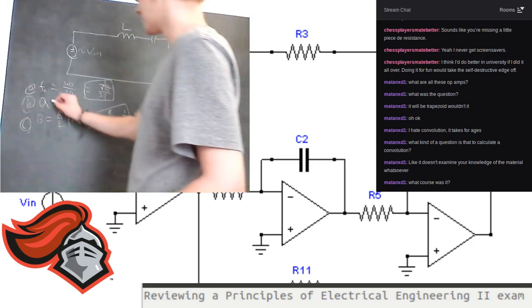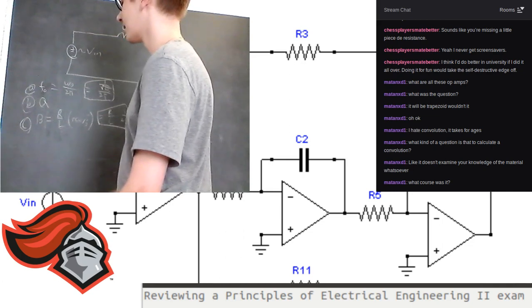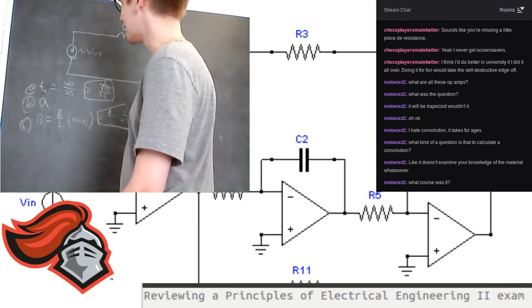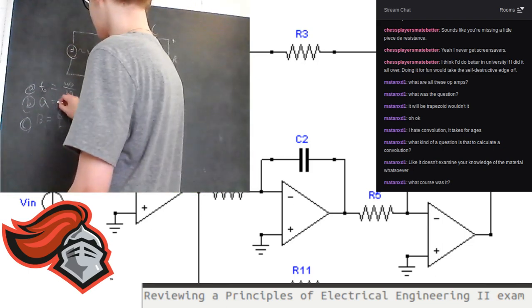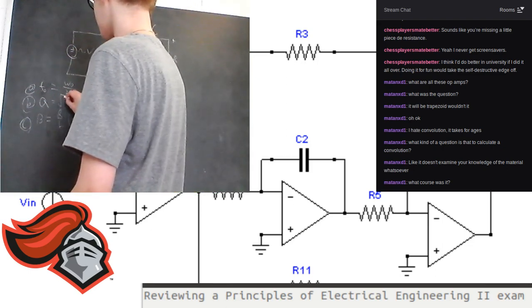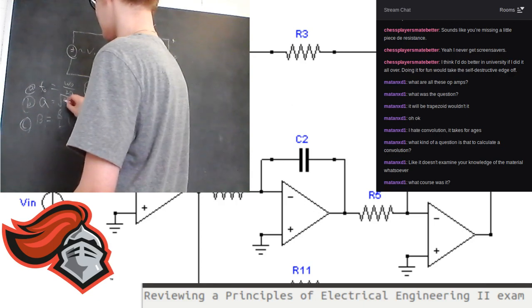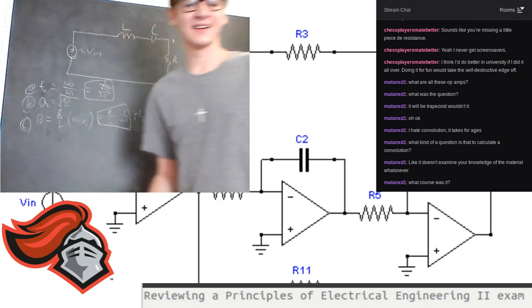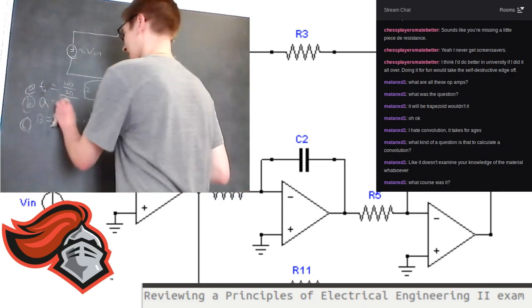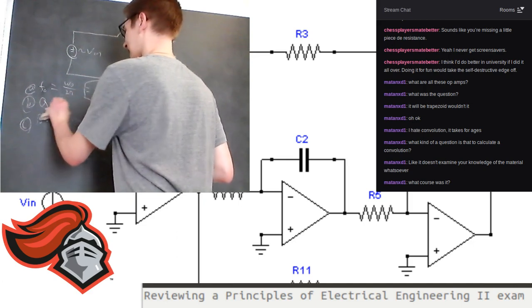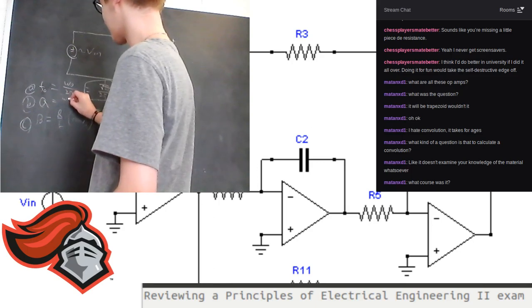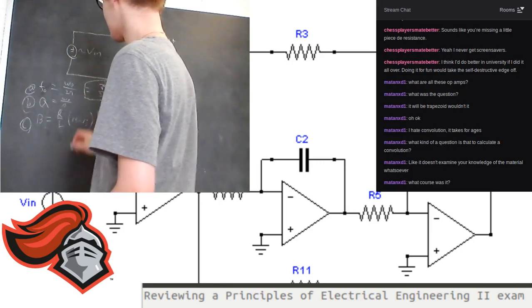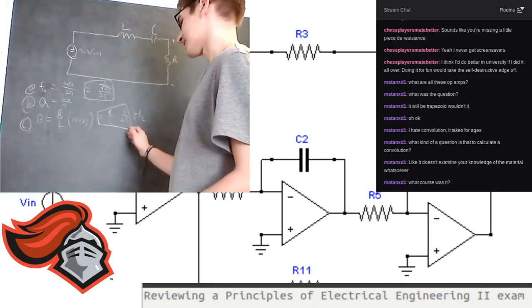And then part B was the quality. Now there is a formula that's like square root of R squared C over L, something like that. I didn't do that. I did the much simpler omega naught over bandwidth, where the bandwidth is in radians per second.